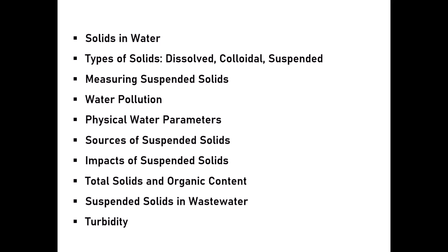And for measuring suspended solids, we take a water sample, dry the residue at 140 Celsius, and weigh before and after. The difference in weight divided by water volume gives the concentration of suspended solids, in milligram per liter or parts per million. Some solids may be volatile, organic, or fixed inorganic, determined by burning at 600 Celsius.